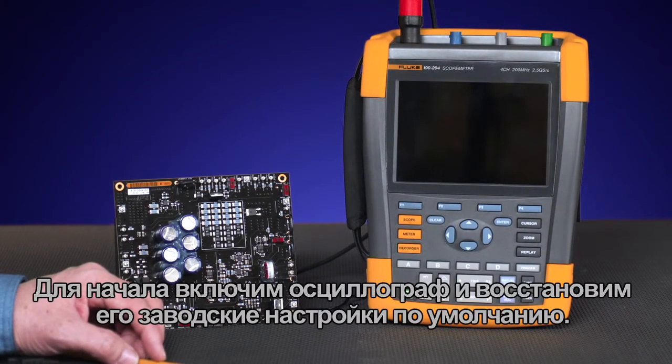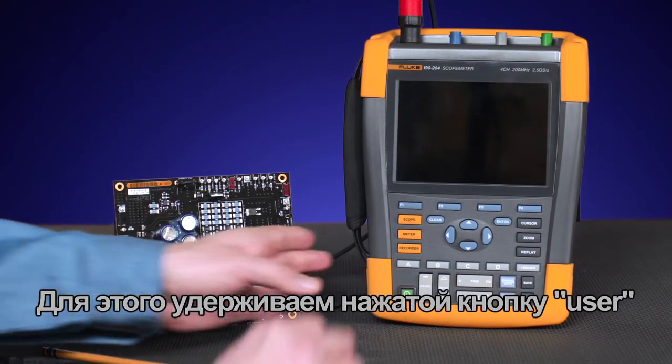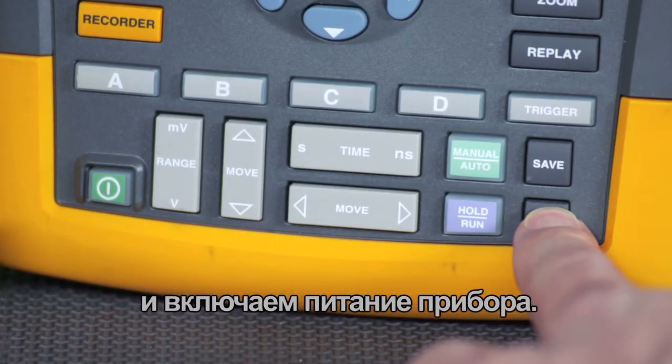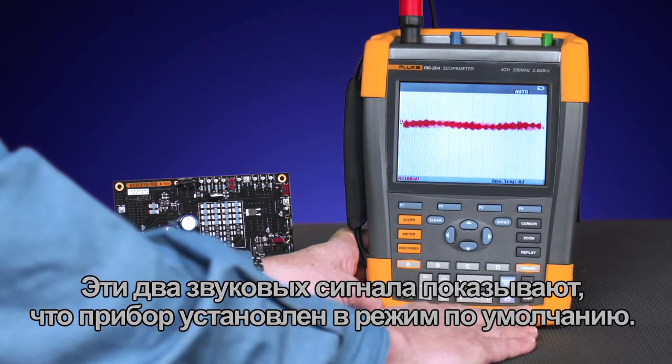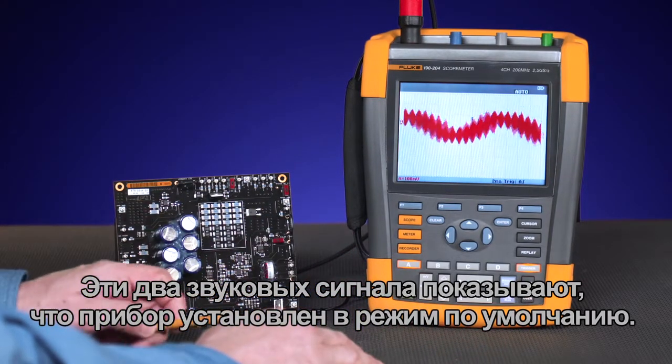First off, we're going to power on the oscilloscope and reset it to its factory default. This is easily done by holding down the user button and then powering the instrument on. You'll hear two beeps indicating that the instrument is in default mode.